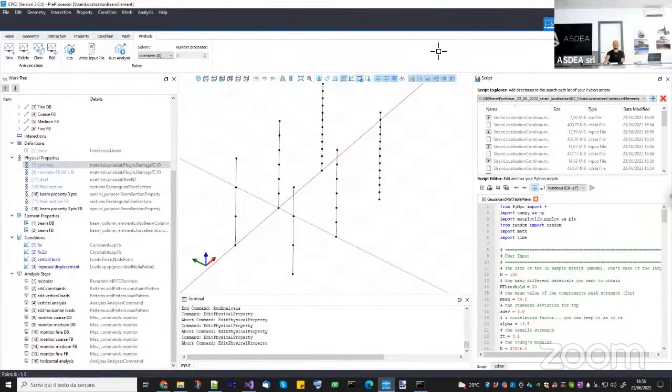So as we said, we have the same problems here, and we can solve them in the same way. The only new notion that you have from here is that when you use the force-based element, you have to account for the fact that the characteristic length is no longer the length of the element, but is the length of the Gauss point. So this is the only difference from the previous model.